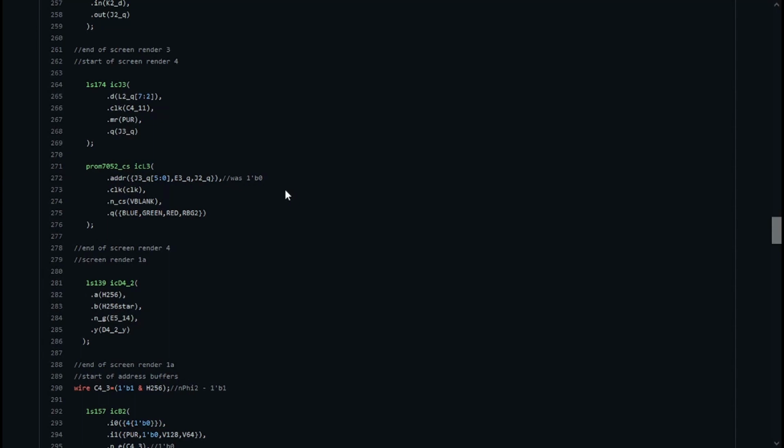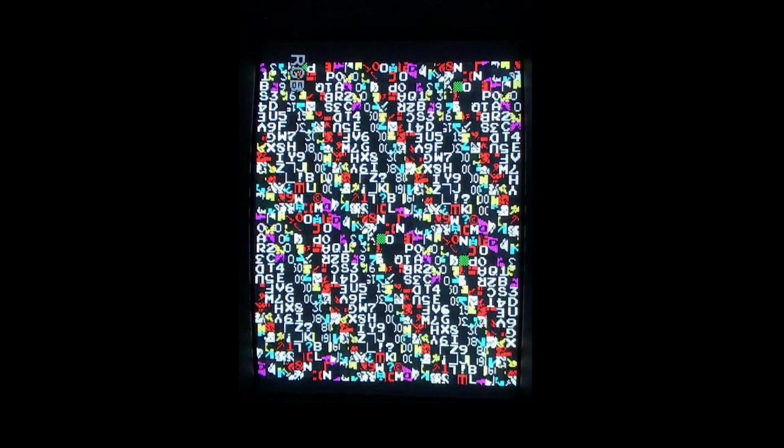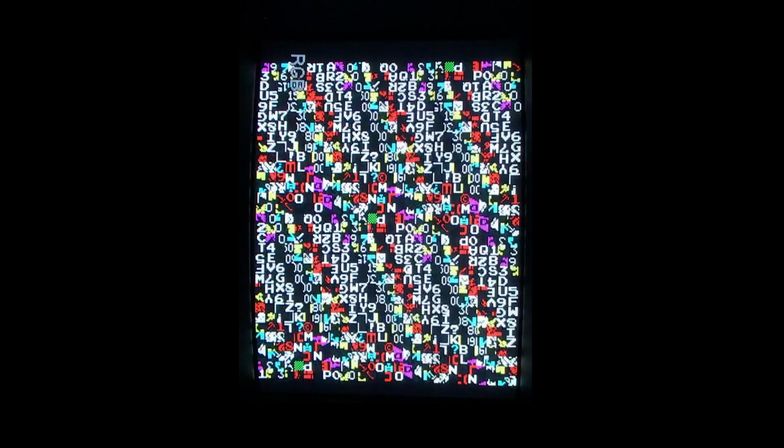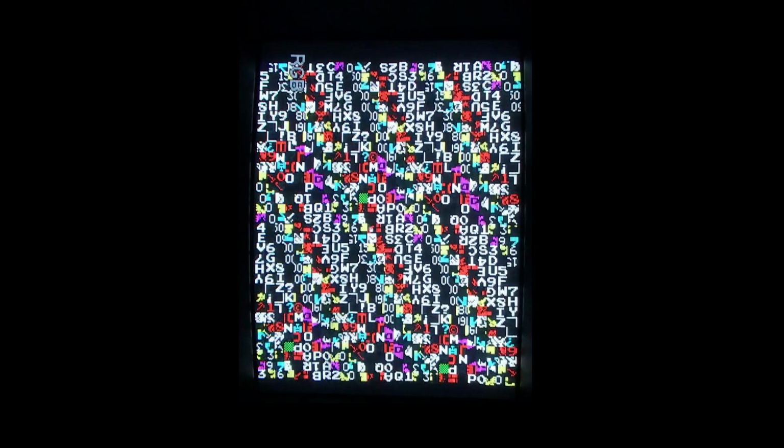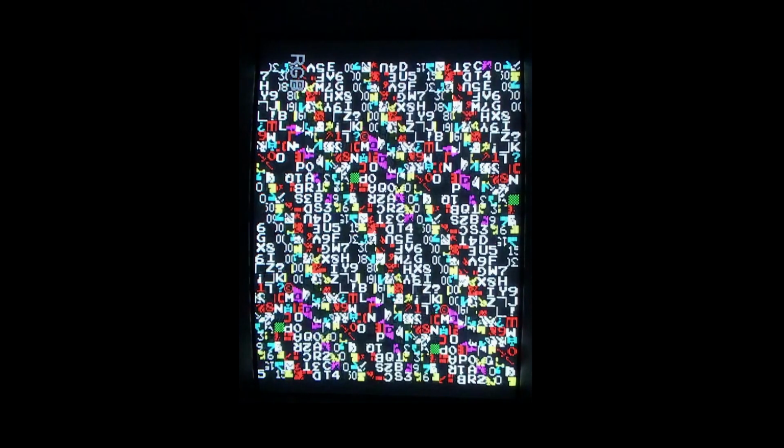And now we've got everything functioning in terms of our rendering system. We've got our tile rendering system and we've got our bullet rendering system, and that's all we need. Now what we can do is remove the constraint of the bullet memory and let the CPU fill it in as normal, and when we fire up the core we get this test pattern running again, but this time in the background behind the tiles we can actually see, if we slow it down, the bullets doing a test pattern as well, and so that's totally normal.